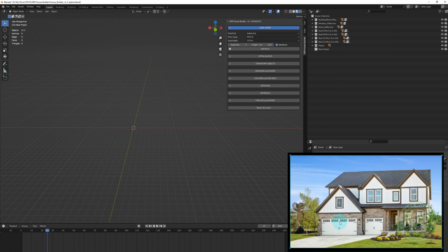So looking at this structure, I'm going to pick something to start with, which is this garage. I've just sort of worked in 3-meter increments. It just makes things easier, and it's close enough, especially for peripheral homes. Remember, we're not going for perfect accuracy here. We're going for close enough for something on the course. In the end, this is going to be 6 meters across. So this is 3 meter, 3 meter, so technically 5 segments moving left to right. And top to bottom, I'm going to consider this 3 meters tall, 3 meters tall, so it's going to be 6 meters to get all the way up here. Let's just use that idea and build.